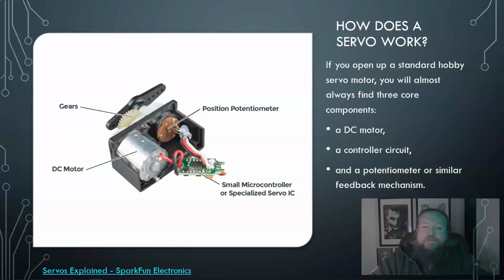That one has multiple different servos controlling things. When it's opening, the actual gripper arm is a mechanism connected to a servo. The same goes for swiveling things around and making it go up and down. So it's that combination of an actual actuator and the physical body combined together into the controller. And using theirs, you can see that he was just using potentiometers as a way to manually control different components of that arm. But you could take out those potentiometers and just put in your own code to control that actual device itself.